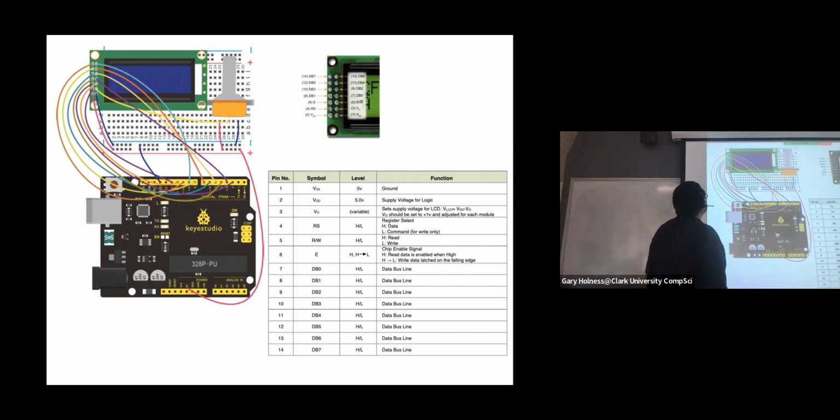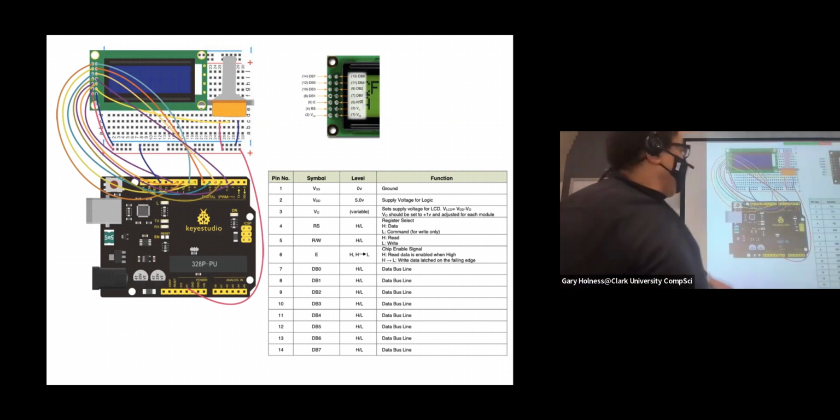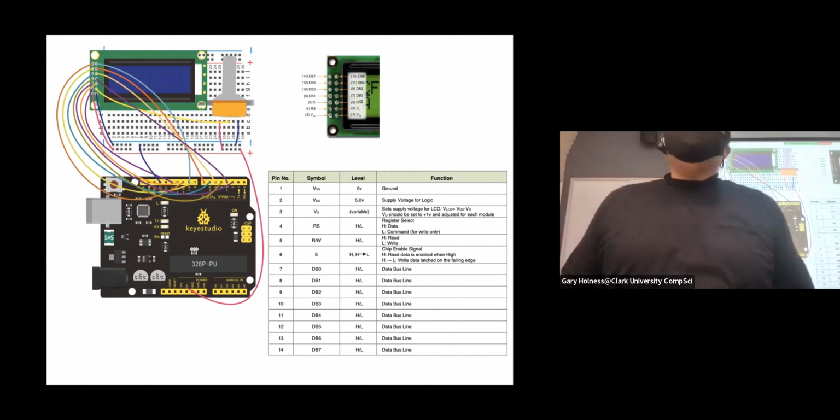Well, we said that the 8 pins DB0 through DB7 is here. So that's pin number 7, 8, 9, 10, 11, 12, 13, 14, right? Starting at DB0. So here you'll notice DB0, this purple, starts at pin 3, and DB7, the orange here, ends at pin 10. So you have pin 3, 4, 5, 6, 7, 8, 9, 10, those 8 in sequence feeding DB0 through DB7, right? They're side by side physically on the digital I/O pins for the board. Okay. Any questions about that?